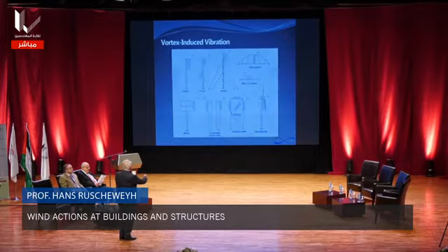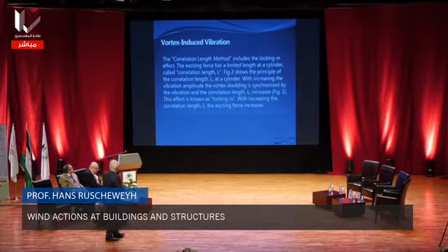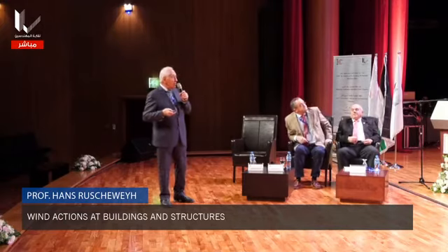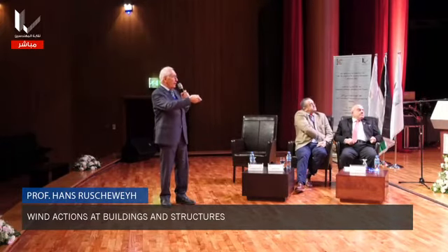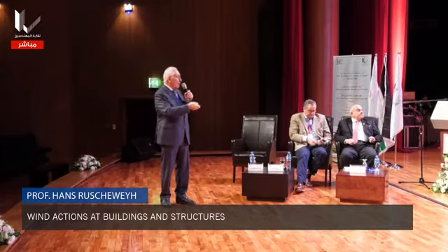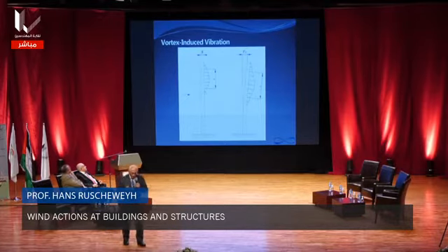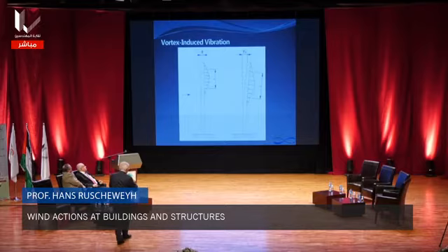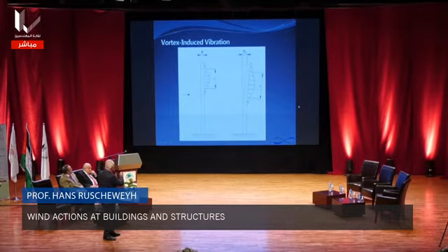The problem is the characteristic of the exciting force, the correlation length method, based on the following effect. If the stack, left figure, is stable, not moving, then you have an exciting force. You see it on the left side, and it is not uniformly distributed. It has a similar shape as you can see there, and the integral length, L, is called correlation length.